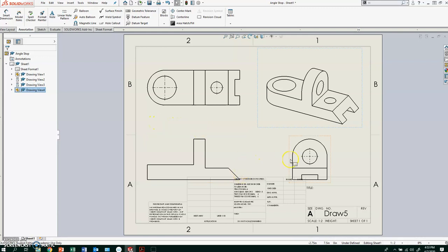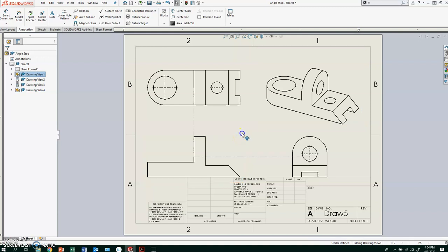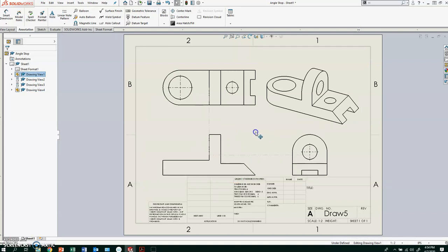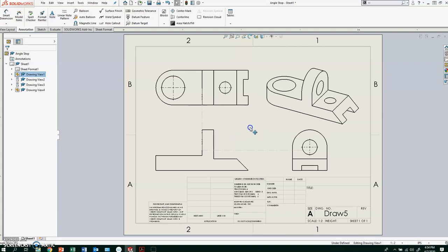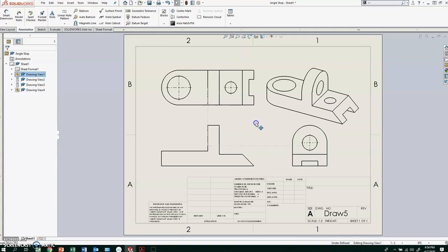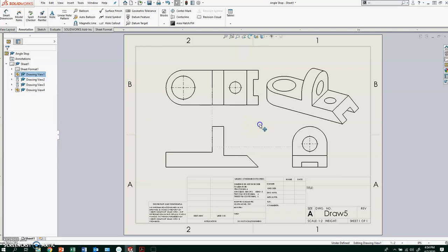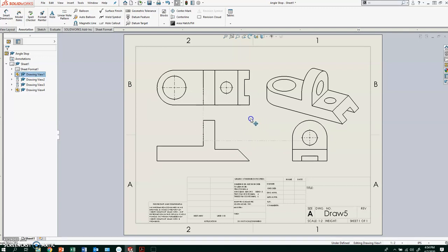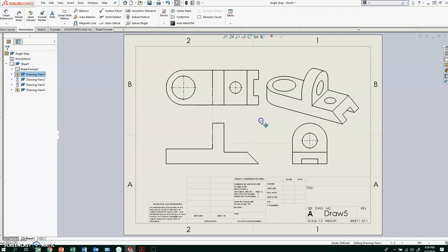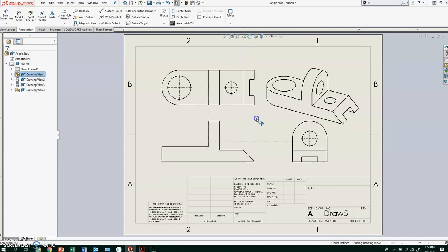You will notice immediately that some of the views are not in the right place. See, this is the title box, and this view actually goes into the title box. So if we put the cursor on this front view around this corner and wait until this arrow appears, now you can move up and down. You can also move left. You can see that if you move one, the other moves accordingly. Remember our multi-line. That means you cannot put this drawing in a random place. Once one is fixed, the other is kind of fixed. So right now let's choose a place right here, about right.